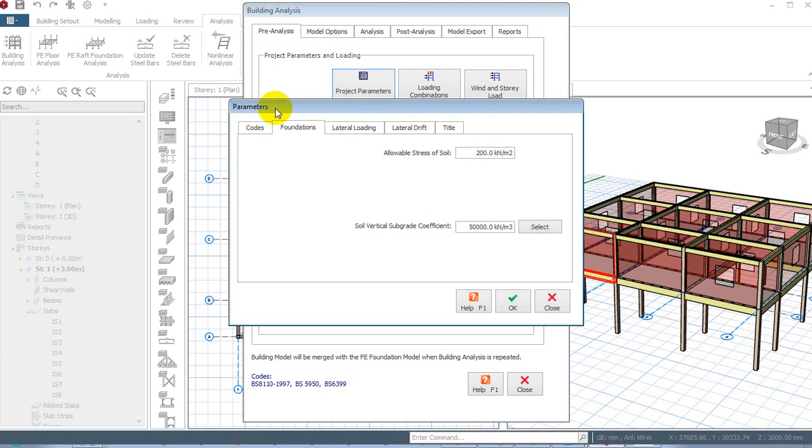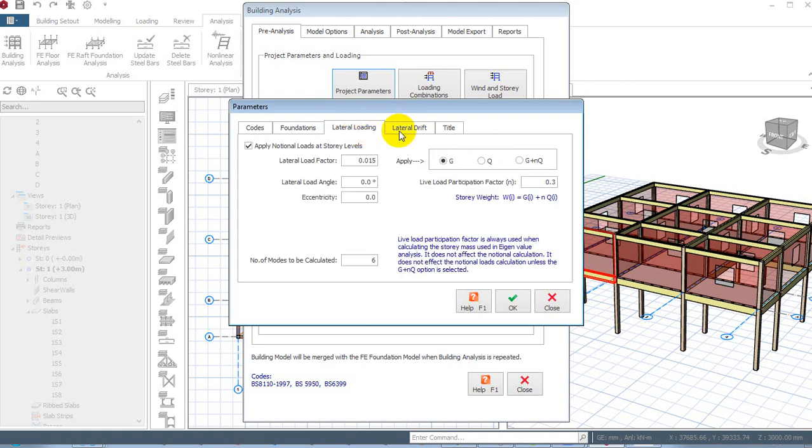Because our soil bearing capacity here is very okay, in this design we are going to be using a pad foundation. So I'm going to be assuming 200 kilonewton per meter square. Even 150 is still very okay. Anything above 100, I think, is slightly okay. Once you're going less than 100, I think it's becoming a bit poor.